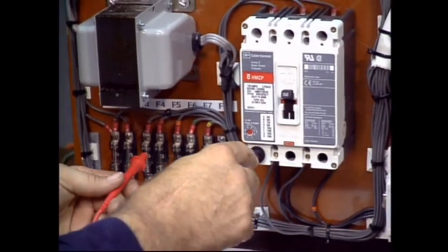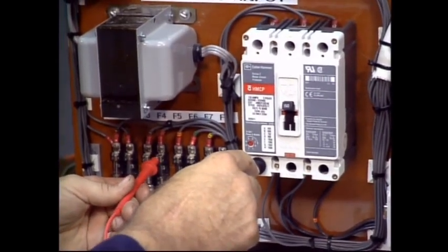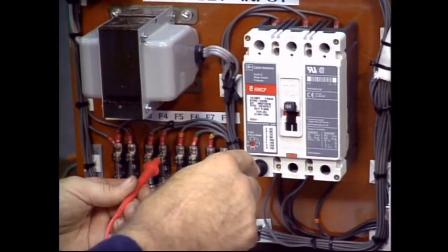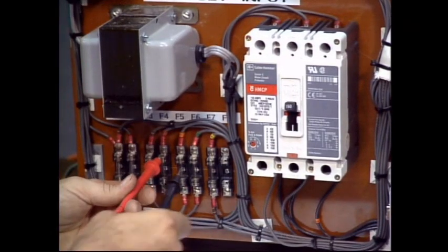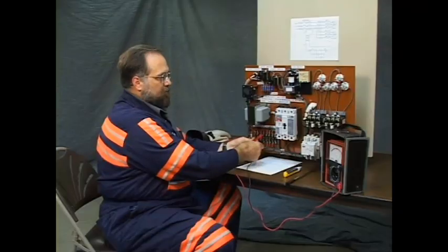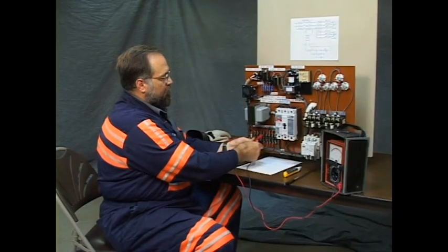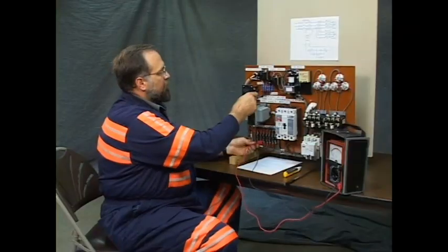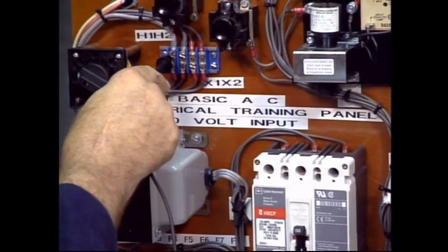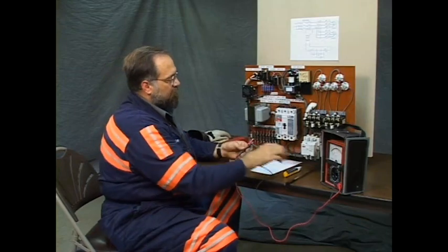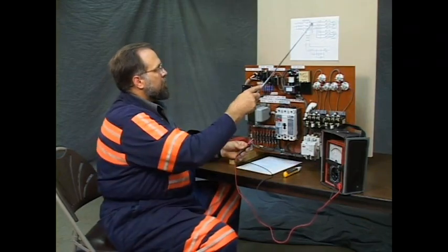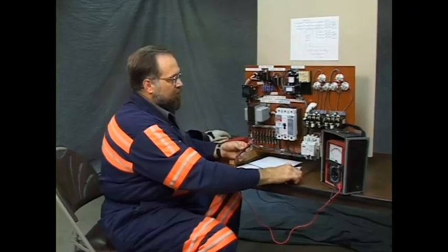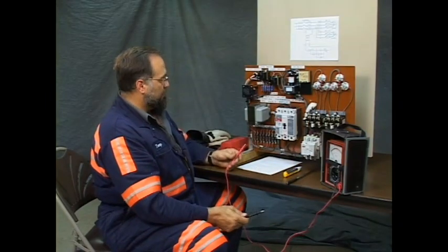You develop patterns in your troubleshooting, guys, and I tend to go from left to right and from top to bottom. L11 to F4 is intact. And through F4, F4 reads good. And from F4 to H1, we've checked this portion of the circuit from L11 through the fuse to the primary of the control transformer and found no open wire or fuse.